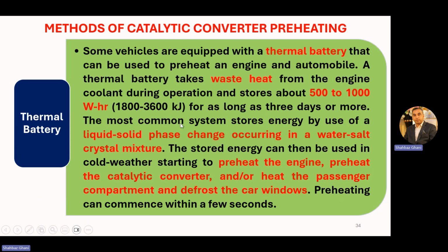The most common system stores energy by liquid solid phase change occurring in a water salt crystal mixture. The stored energy can then be used in cold weather starting to preheat the engine, preheat the catalytic converter, and or heat the passenger compartment and defrost the car windows. Preheating can commence within a few seconds.